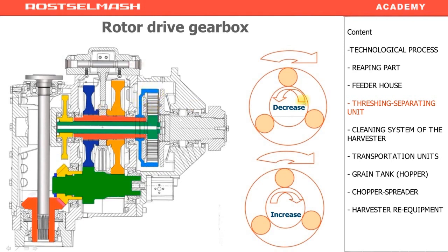Inside the crown, there are satellites. If you look from the top, the satellites are the three circles. The green gear in the center with outer teeth is called the sun gear. The sun gear does not depend on the red shaft. Here it rotates freely, so the rotation speed does not depend on the selected range. It is firmly connected with the yellow gear. The yellow gear is engaged with the hydromotor. This gear is controlled with a hydrostatic transmission.